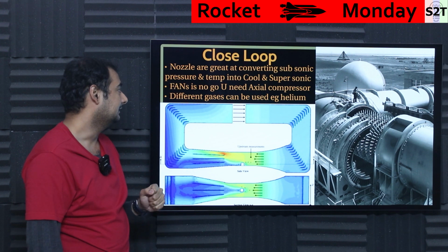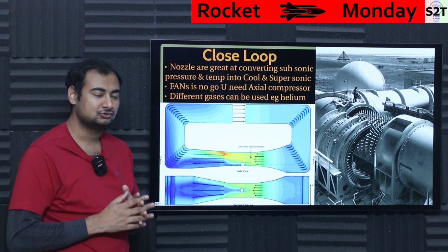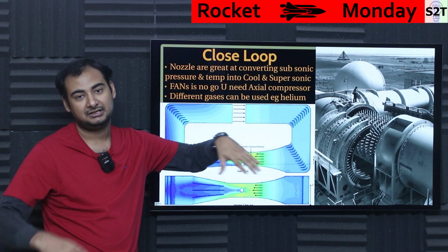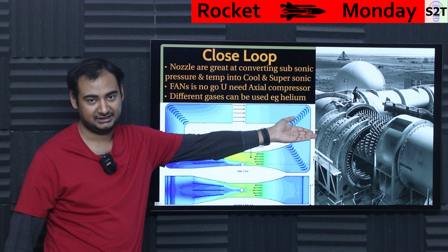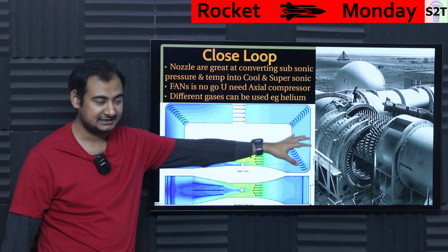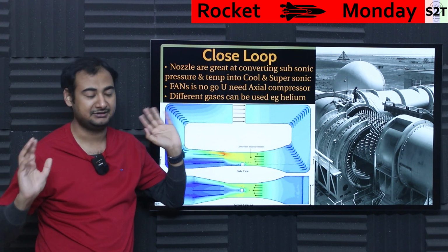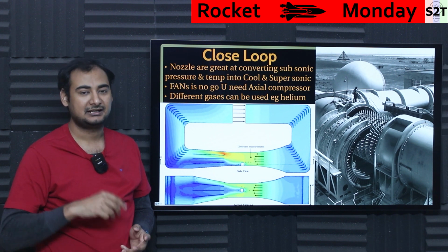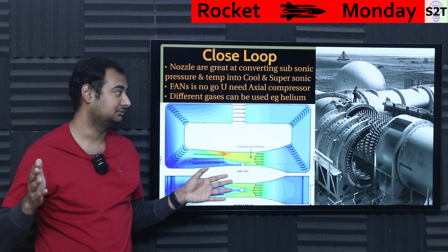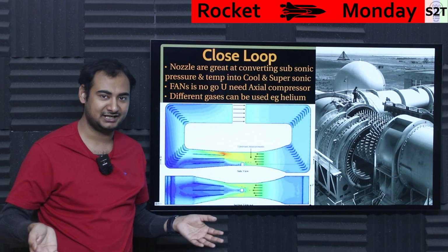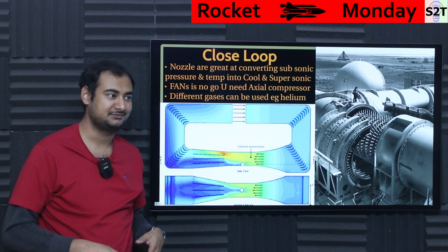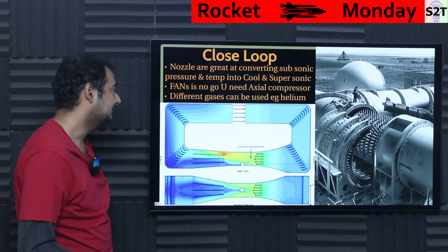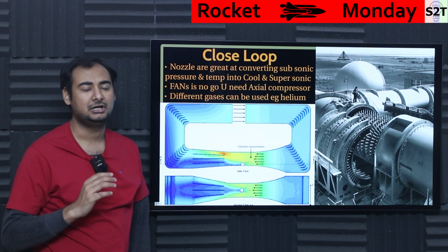So you get that. Now at that point in time, the pressure required is so high that a fan no longer works. You need these puppies. Basically, a jet engine had a baby with a giant. This is what they are. Huge puppies. These are axial compressors and they are giant. I mean, they can easily consume hundreds of megawatts, and not to mention the RPM has to go down because, again, the size is huge. Like building size, they cannot spin at jet engine speeds like 100,000 RPM or 50,000 RPM or even 10,000. They have to be under 1,000. But they do consume power and they compress a hell of a lot of air.